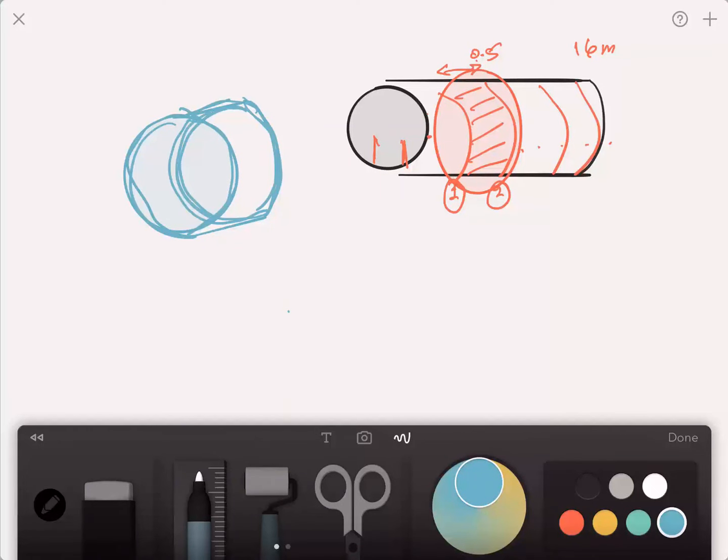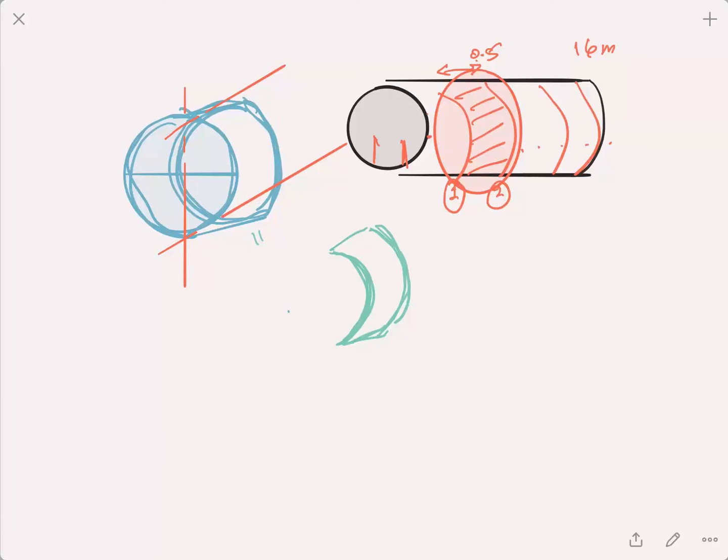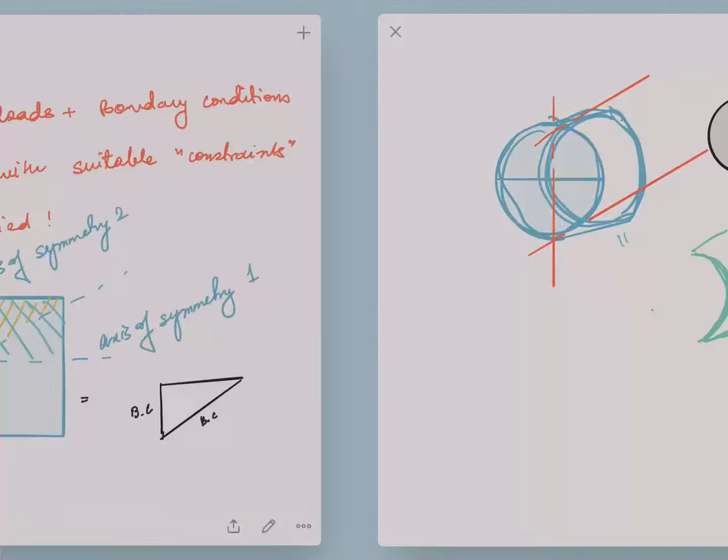And then I realized, hey, that's also something we can reduce if it is completely symmetric. And in my case, it happened to be symmetric about this axis. That means the loads were all the same, and so was the geometry. So I could actually reduce it now to one side, half of the fuselage with the two frames on either side. So that was one of the ways of reducing the size of the model, and this was just done on the basis of symmetry.